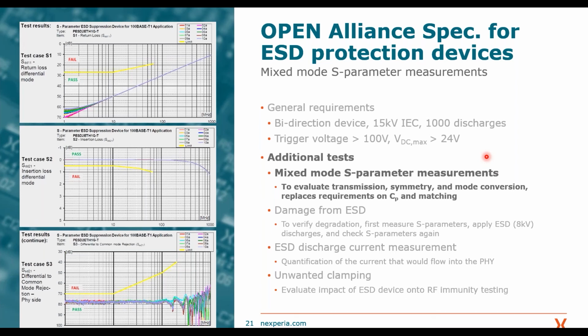For those of you who are not familiar with RF engineering and scattering parameters, specifically, these give you an indication of how much of the signal which you put in your system will be transmitted or reflected. So the reflection is shown here with this S11 parameter, also called return loss. And here the reflection should be as small as possible. And there are also some limits here in yellow, and you need to be below the limit.